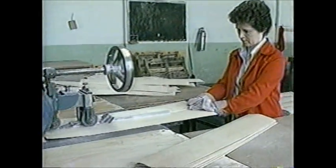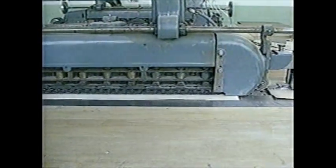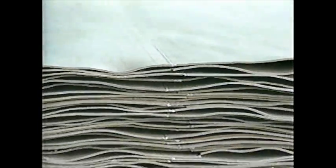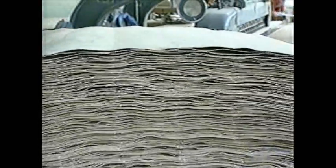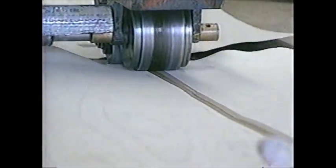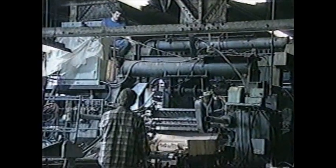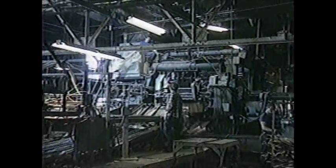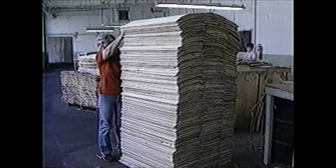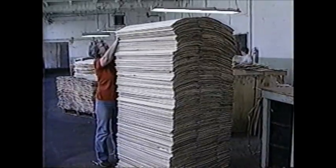After trimming and glue application, the packages of veneer are taken to a splicing room where the sheets are edge-glued in a splicing machine. Several edge-glued panels can be joined to produce wider stock. Pieces of lower grade veneer used as core stock are joined using paper tape. The hardwood veneer production of Tupper Lake is intended primarily for the specialty hardwood plywood market, such as furniture and cabinet pieces and automobile and sporting good uses, rather than hardwood wall paneling.